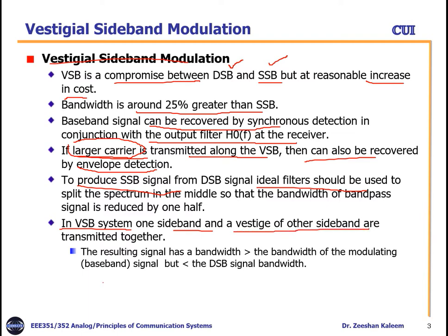As I mentioned, okay, let's plot it as well. If this is the case of a double sideband, for example, this is your upper sideband and this is the lower sideband, right? And I am just plotting the positive side only. This is the case when we have a single sideband modulation, right? There is no other band. So this is the single sideband case, SSB, and this we call DSB.